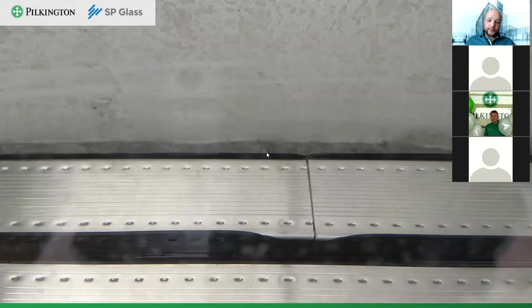That's one thing. And second thing, you can use a black spacer, because on the black spacer, the butyl expansion is much less visible. So that's how to deal with the probable butyl expansion. But the most important thing for an IG unit producer is to control how much of this primary sealant you're putting on your spacer, and you need to control it regularly. Basically, in all good factories, this is done every day at the start of production.